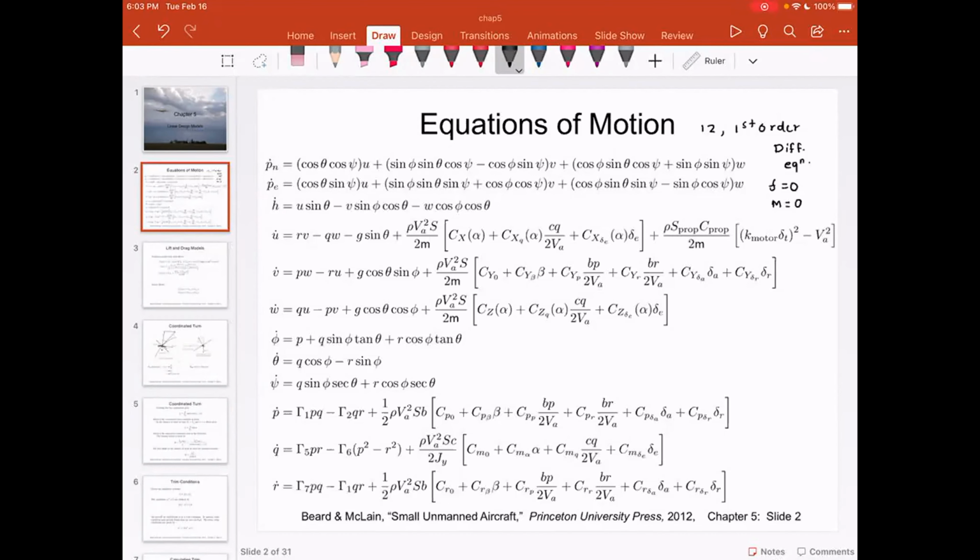I want you to look at some of these important parameters mentioned here. This is the rudder deflection. This is the aileron deflection. This is the elevator deflection. These are the control surfaces that are controlling the behavior of the aircraft. And you have the external thrust provided by the prop and the resulting torque that needs to be compensated so that the aircraft does not self-roll.